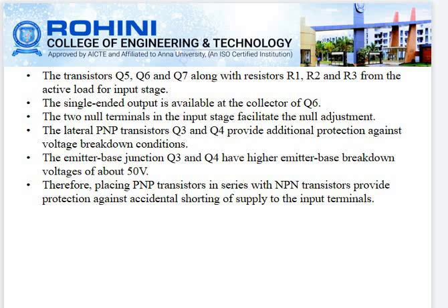The two null terminals in the input stage facilitate the null adjustment. The lateral PNP transistors Q3 and Q4 provide additional protection against voltage breakdown conditions. The emitter base junctions of Q3 and Q4 have a higher emitter base breakdown voltage of about 50 volt. Therefore, placing a PNP transistor in series with an NPN transistor provides protection against